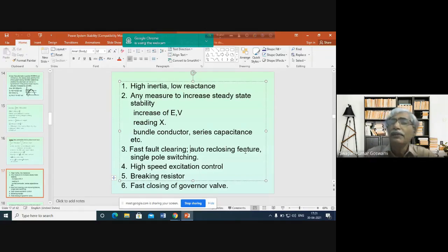And if it flows through some other path, then those paths again may become overloaded because of the flow of this heavy current or heavy power. As a result, when overloading is taking place, it may cause the total system to collapse because of the tripping of transmission lines one after another. This type of situation may happen because of the occurrence of a fault. But remember that most of these faults are transient in nature,